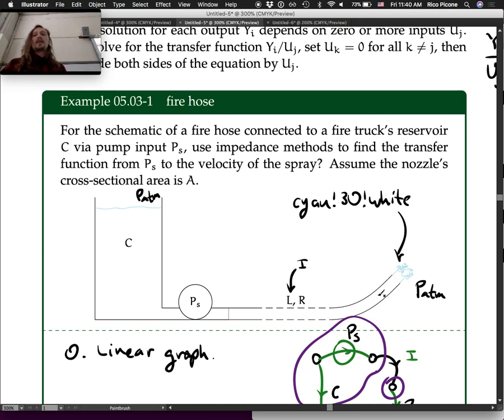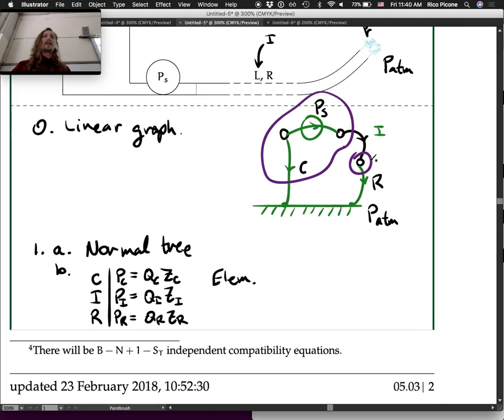QR, which actually there's only one flow rate going through the whole thing, right? It's going to have different cross-sectional areas, but our continuity equations are telling us that we have one loop here. So the flow rate's got to be the same for all of these elements. So we want to find flow rate, QI, QR, QC even. Any of those would get us to our result.